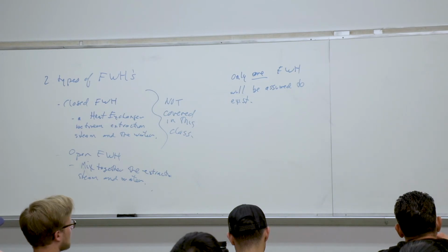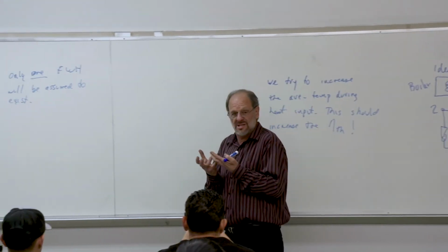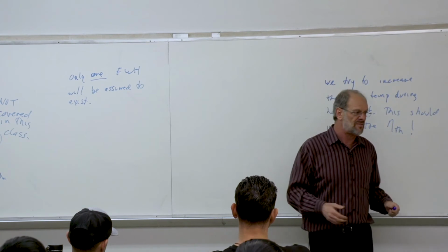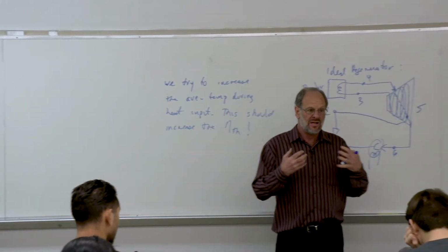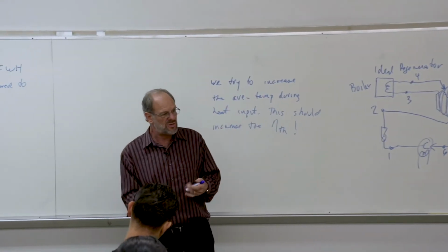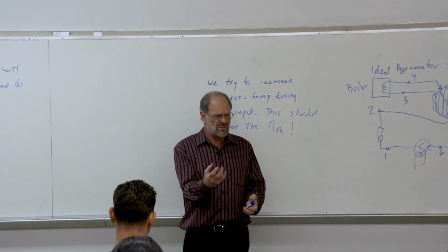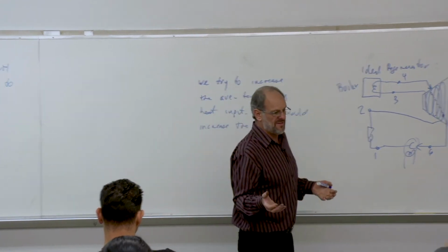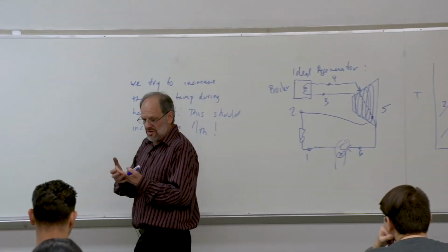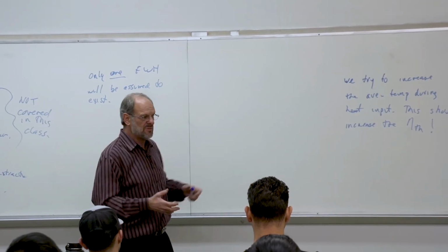Okay? When you have water, water being a liquid, all liquids have the ability to contain, or if you will, have a certain amount of gas absorbed into them. Any water that exists in the environment will actually have some air saturated within that liquid water. This is something you know sometimes when you turn on your water faucet, you relieve the pressure as it hits the cup, and the water starts getting all fizzy. Well, where did that fizziness come from? Well, that's just air that was previously dissolved in the water, and the water in the pipes is at what, 100, 150 psi, but when it goes into your kitchen, it's at atmospheric pressure.